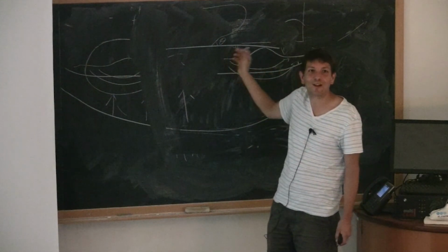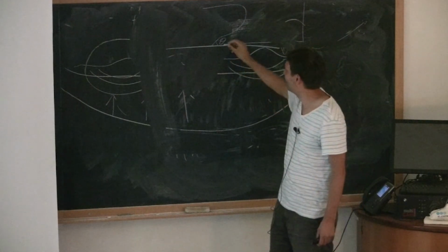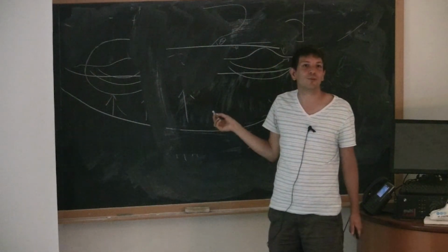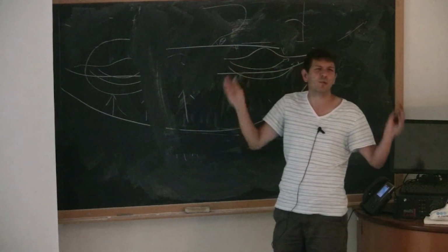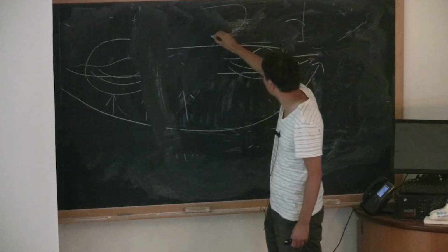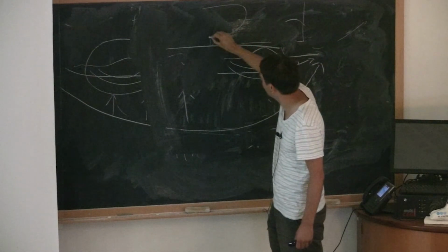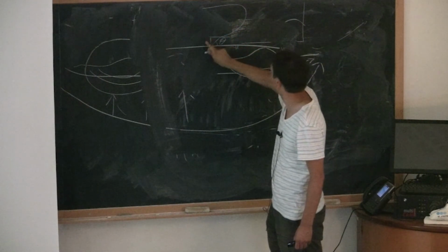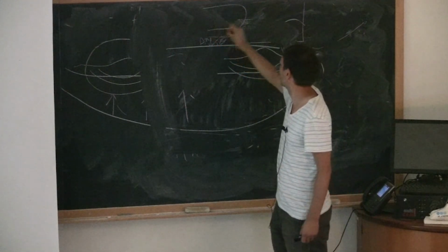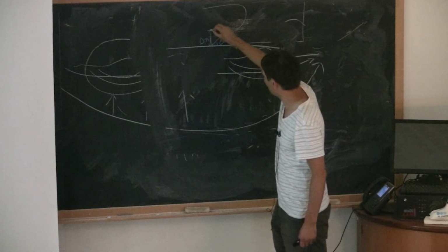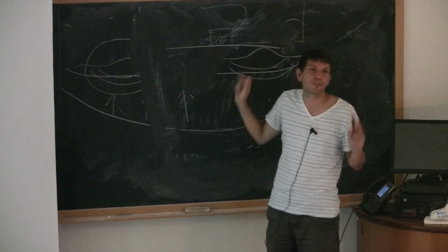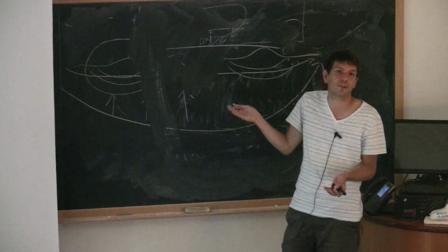The thing is, it applies only if you are able to capture all the length scales close to the wall. In reality, this is not something you can do because you would need a very huge grid. And probably the first grid cell you will have in your mesh will be something like that, here delta x, which means even larger. So you have to upscale this information, and the Cox-Voinov is an effective contact angle that includes this viscous bending.